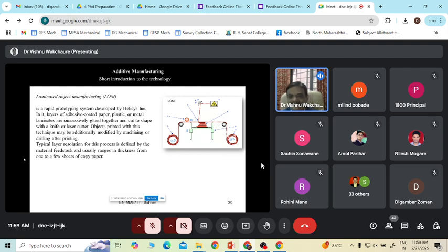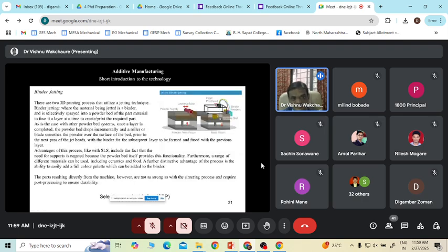Okay, this is the laminated one, as shown earlier. So this is the view. Layer by layer they are cut and the material is going like this. Here you can see that it is a kind of blanking process. Whatever blank is required to be placed here will be cut through laser, then the next blank, and likewise. So this is layered laminated object manufacturing.